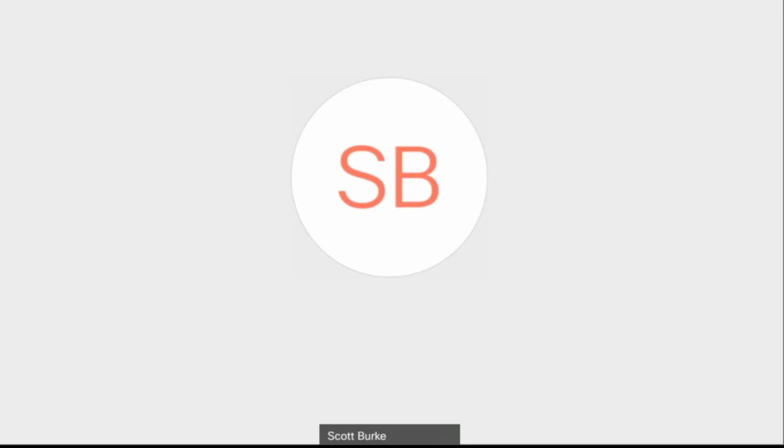So another question here: when should teams be set up as the project admin side, which creates a folder structure automatically? So basically here, the administrators of the site, of the whole hub, they're the ones that create projects, and they can assign someone as a project administrator. When you're creating a project in either Docs or Design, there's an option when you first turn on Docs that you can copy the folder structure from a previous project and make it the same folder structure in your current one.